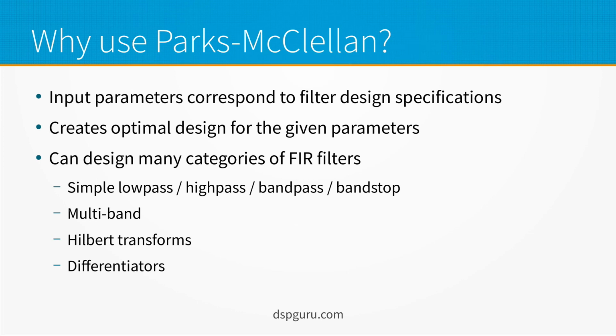So why is the Parks-McClellan algorithm so widely used and so popular? Its input parameters correspond to the normal digital filter design specifications that you create in creating an overall DSP system. It creates the optimal design for those parameters, and it's also quite flexible. It can design lots of different categories of FIR filters.